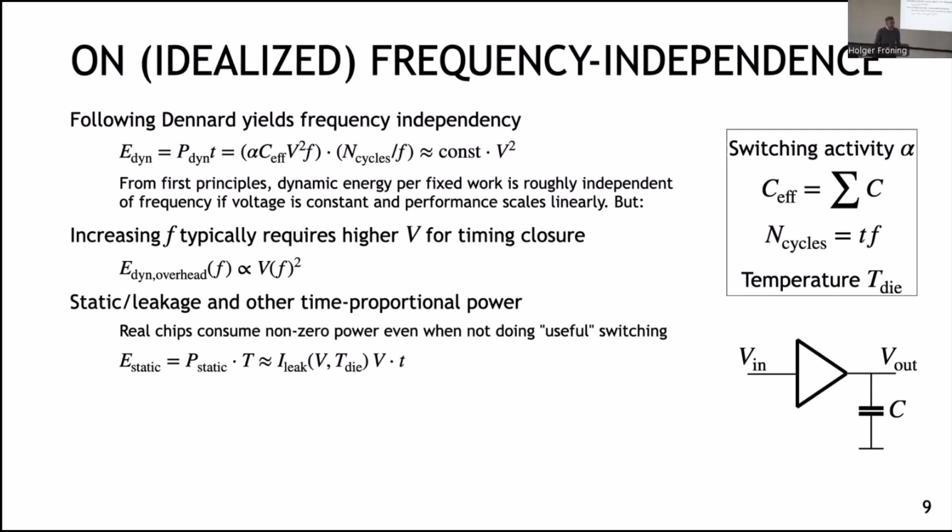Secondly, of course, there's leakage power. So a large fraction of the overall power is simply being lost, even though we don't do anything useful with it. This has gotten down a lot recently. For the recent GPU experiments, we saw that we have an idle power of 20 watts, and I would assume that to a large fraction is actually the leakage power. And this has been way, way worse in the past. So apparently people have been doing some nice jobs here with clock gating and similar things.